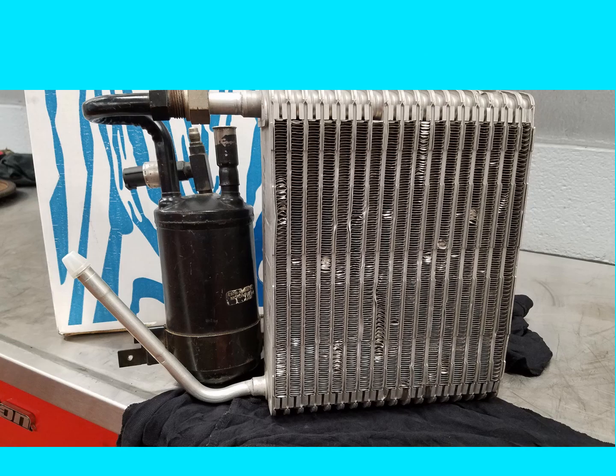Here's a picture of an evaporator core out of the vehicle. This came out of a Ford Ranger, I believe. And so it gives you an idea of what an evaporator core would look like. The black component hooked to it is the accumulator. That would be between the outlet line, which is right at the top. This is the outlet. This is the inlet right here. So the liquid refrigerant's flowing in.